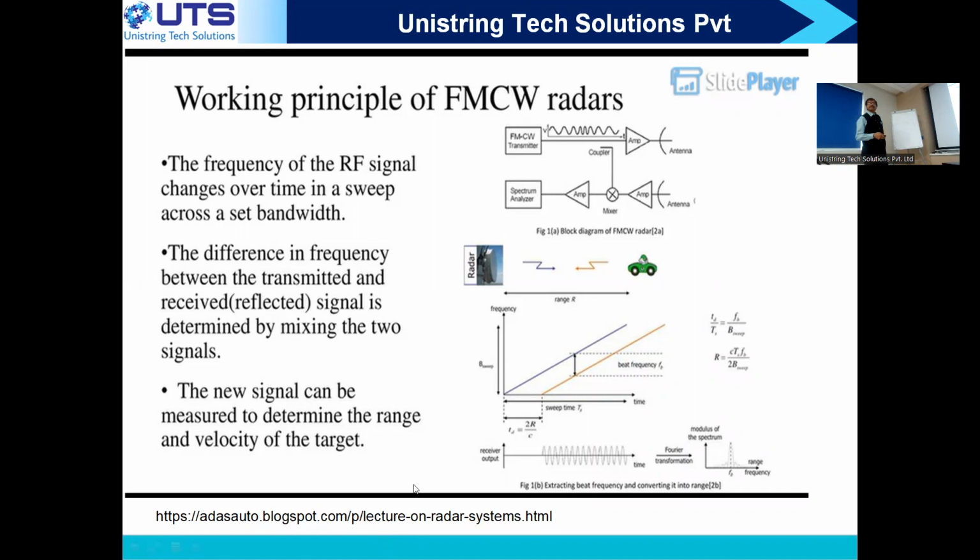So look at this figure. It explains the range. This is the instantaneous frequency, I should say. Instantaneous because whenever something is on the time x-axis, it is called instantaneous. So this is the instantaneous frequency of the received signal. At any instant of time in my mixer, I take a copy of the transmit waveform and mix it here.